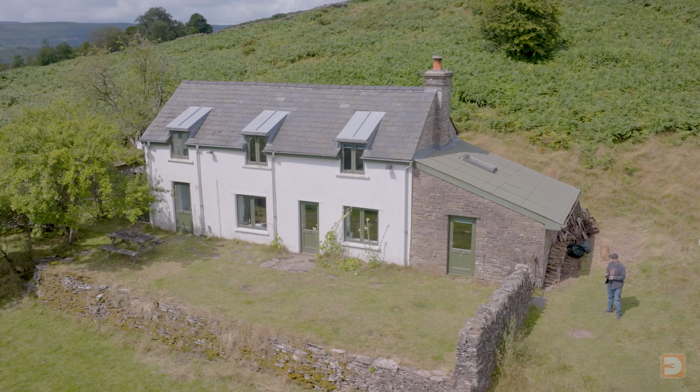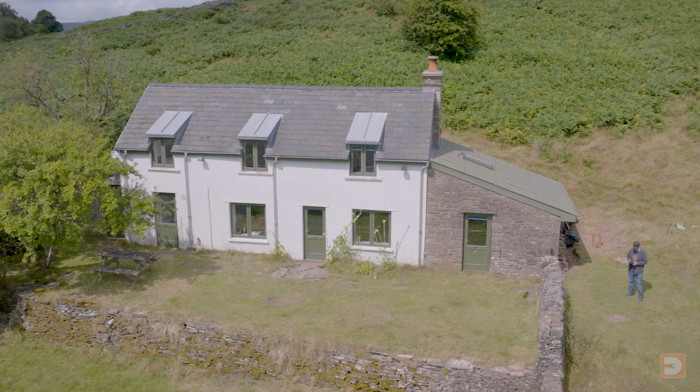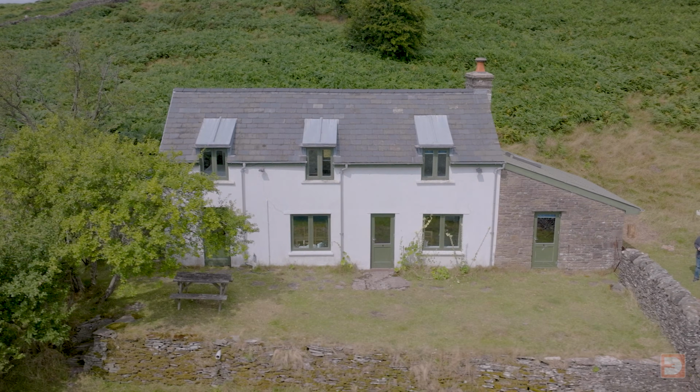Not only was the lighting harsh that day, as with the statues, but it was also quite windy. Whilst the drone handled the wind fine and short exposures prevented any motion blur in the photos, the wind can still cause an issue with photogrammetry. Wind can be particularly problematic, as not only does it mean that objects like branches and leaves of trees can be in completely different positions or even shapes between photos, but if you're shooting in harsh lighting, the shadows from those objects are also going to be in different positions and shapes on your object and the surrounding area, and again that will differ between each photo.